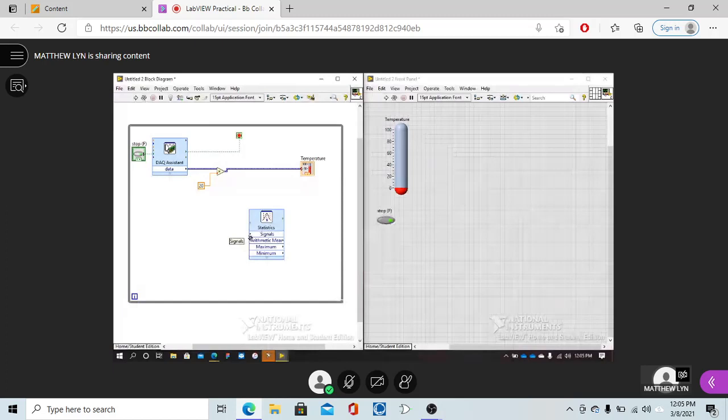Note you could just click it, go to numeric, and let's see where this is. Maybe it wouldn't be on this one. Numeric. All right, so numeric control, here it is. Numeric control, drop it there. So this can enter the value, and you would have to now link here with the input for the multiplier. You see it? Yeah, man, seeing it. Thank you. Cool.